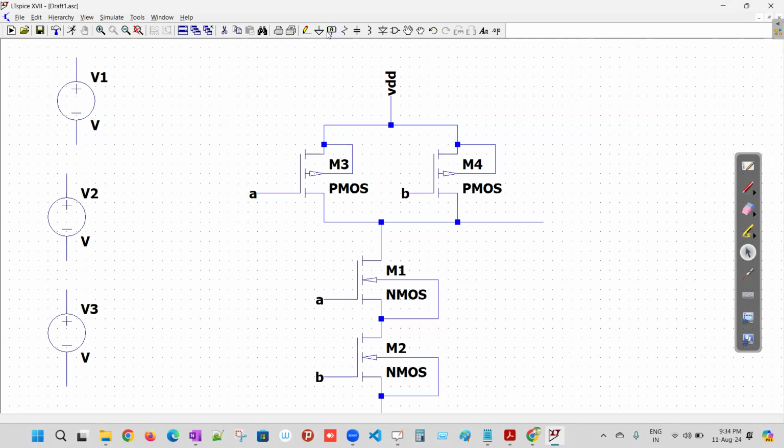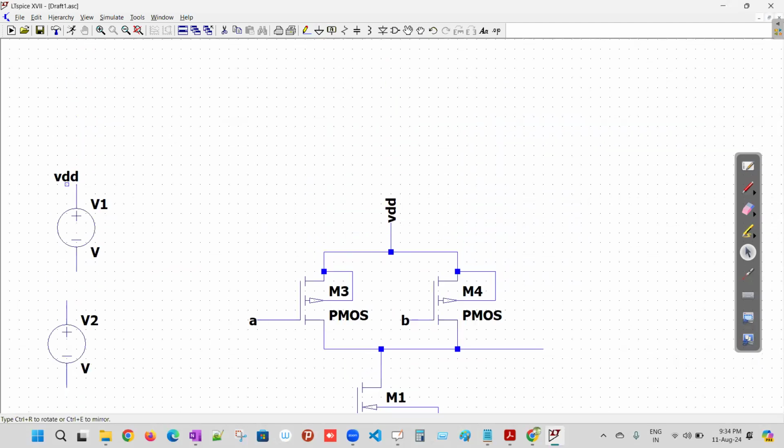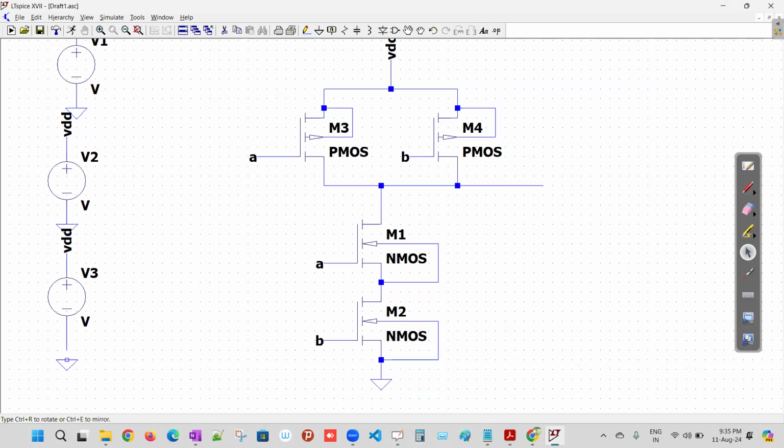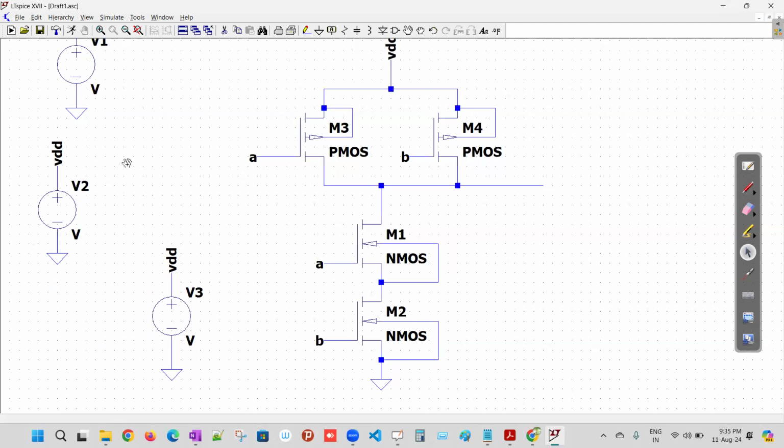So now you can connect the net label here, VDD. This is VDD. And later I will edit here, here. And here I have to connect the ground. So to connect the ground, this ground is here and here. If you find an overlap, then go to this one, move, select that portion and move it like this, away from that. Same here also, like that.